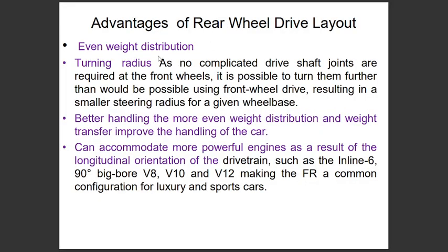Advantages of rear wheel drive: even weight distribution and turning radius. No complicated drive shaft joint is required for the front wheels, so it is possible to turn them further than is possible using front wheel drive, resulting in a smaller steering radius for a given wheelbase. Better handling: even weight distribution and weight transfer improve handling. It can also accommodate more powerful engines as a result of longitudinal mounting, with additional dimensions such as inline engines.